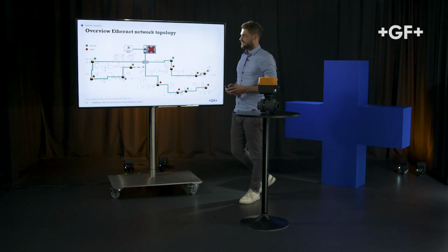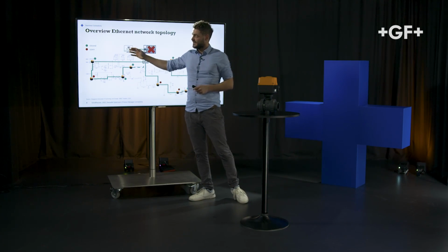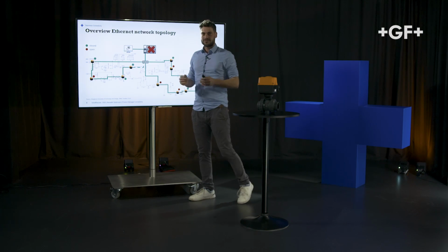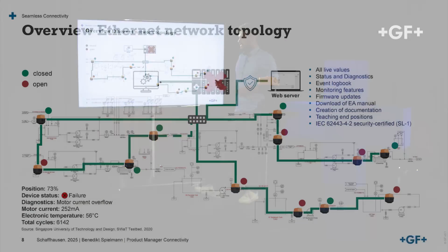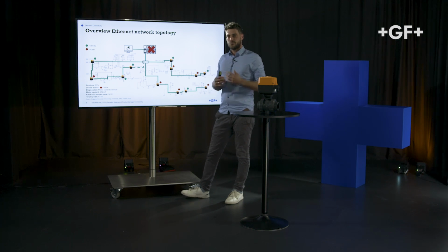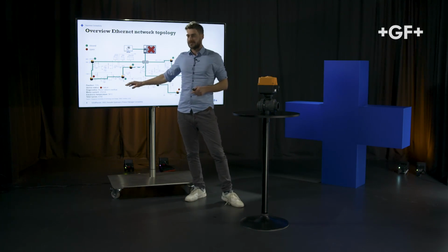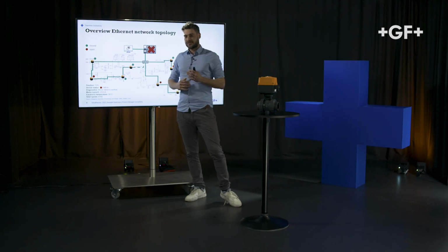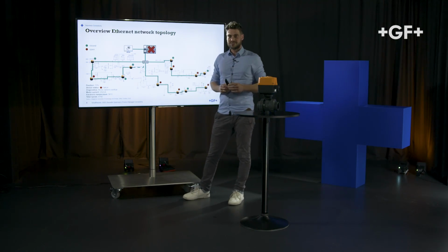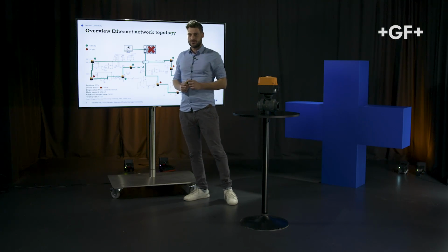Let's take a look at the data side. Of course, the basic functionality of the actuated valves is still maintained, which means it's possible to steer, open or close the valve. In addition, there is so much additional data available, like the motor current, the device temperature, and also a lot of diagnostic events. So the device monitors the health status of itself and can give the detailed diagnostic event to any kind of customer system, which brings a lot of increase in efficiency on the customer side because there's no need to go locally to the device to check the root cause of the error.